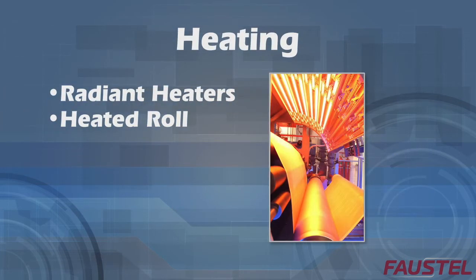Radiant heaters and heat transfer media such as hot oil and electricity are methods used to provide energy to the laminator. Each approach has advantages, with maximum temperature and speed of response being significant factors in selection. Product uniformity can only be assured if the process conditions across the web in the transverse direction are consistent.